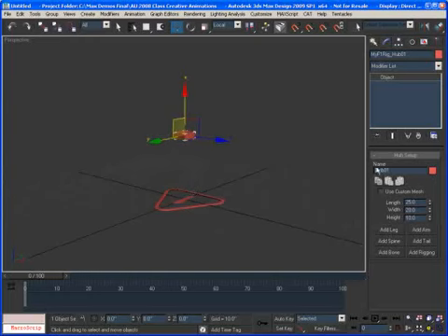You see that the pelvis is called Hub 01. I'm going to rename that pelvis. And if I deselect and reselect, you'll see that it automatically renames the pelvis, which is kind of cool. All the bones will also be renamed automatically when you start to add more links or spine or legs or things like that to the rig. So I've got the pelvis done. And from the pelvis, you can see that I can add a leg, an arm, a spine, a tail, an extra bone, or add more rigging to it. We're going to use all of these tools to build our rig.